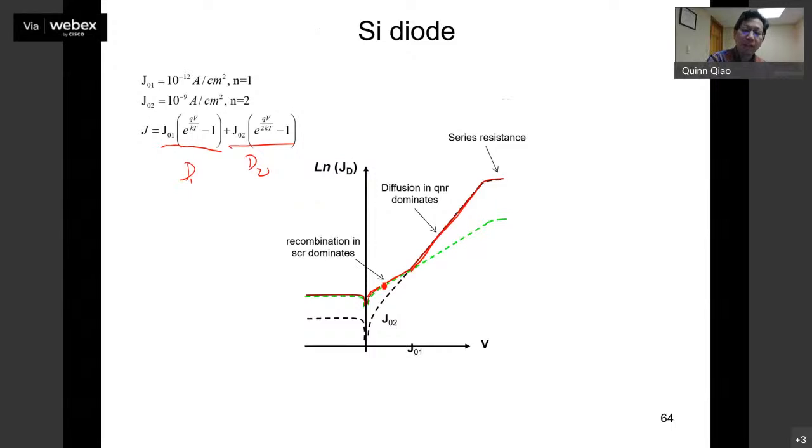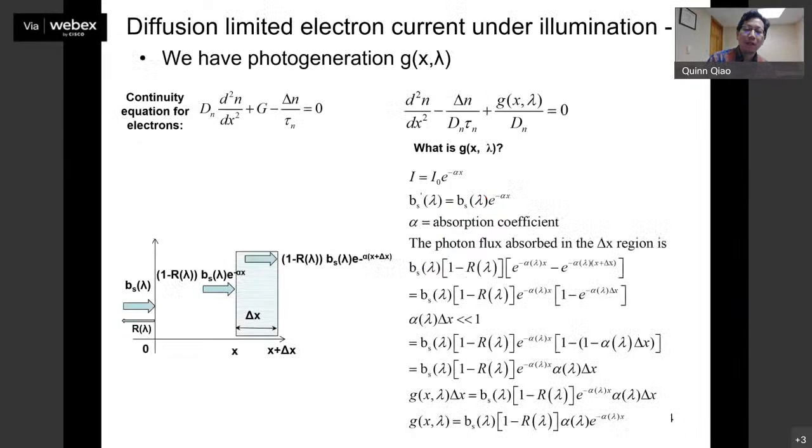That means more flat shows more, while VI will be more steep, because V is the x-axis and I is the y-axis. So when it's more flat, that tells you recombination n gets closer to 2. When it's more steep, that will be the diffusion, n getting close to 1. You can plot it easily by yourself.